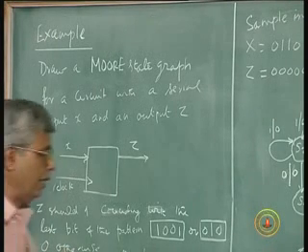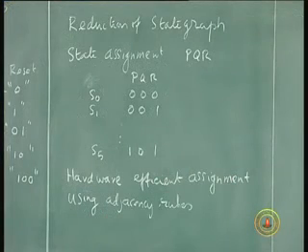And also this time we will not identify overlapping patterns. I will give you two variations. That means when I clearly have a 1001, output will be 1, and that 01 will not be considered as a part of another sequence. Again it has to start with a 0010. Only then can it be a valid pattern. So non-overlapping. So I am going to reduce this. Overlapping of the patterns need not be considered.